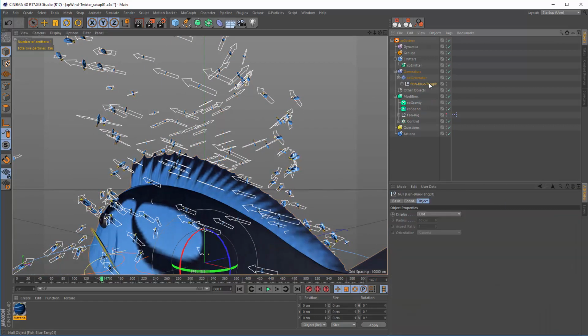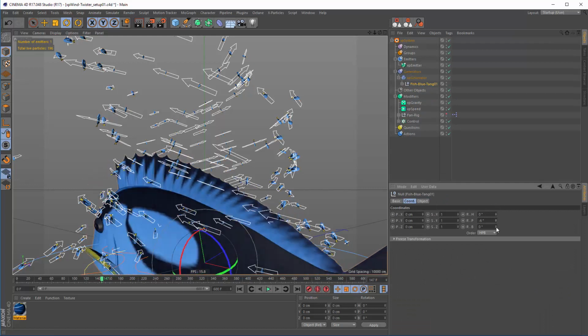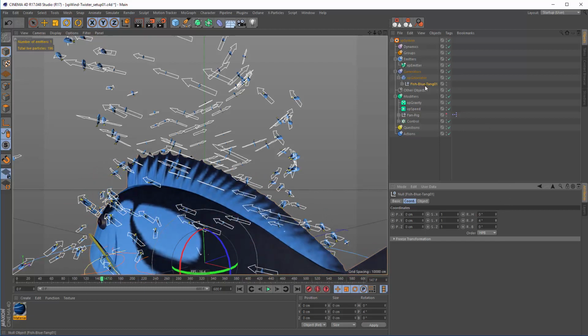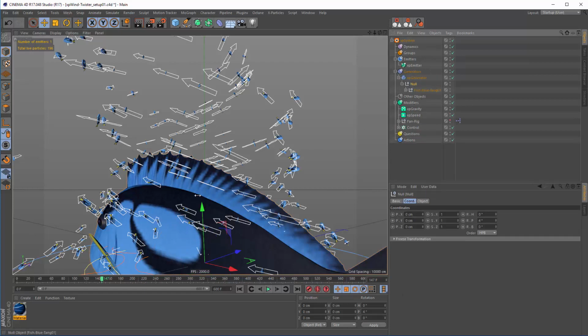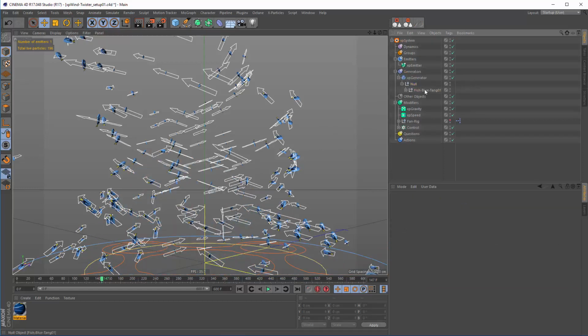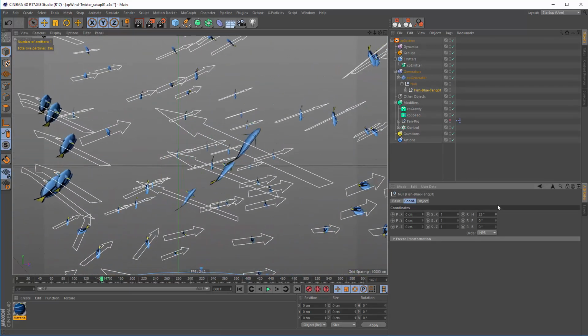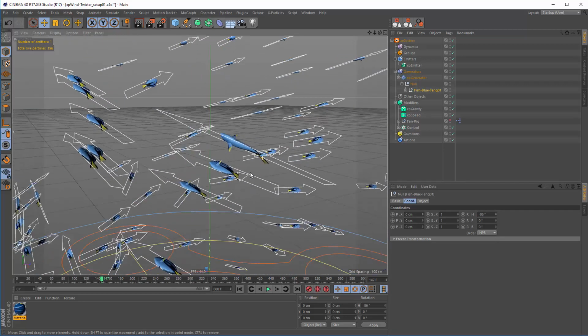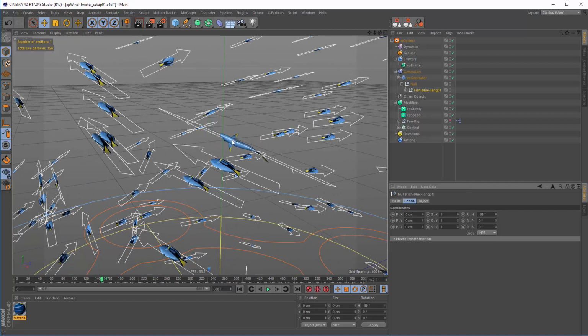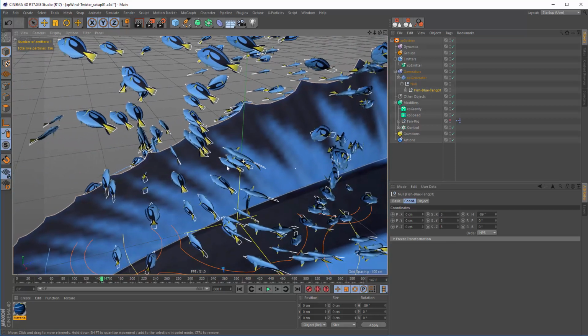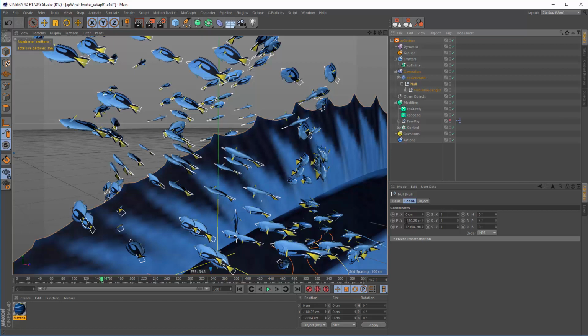All right. So right now, if we want to rotate the fishes correctly, it only affects the source fish. So let's put that into a null object, press Alt G, and let's move that down so we don't see the big one here. All right. And now we can go into our scene and rotate the fishes according to the particle rotation. And we can increase them as well, like scale of 3. All right. And let's move that out of our scene again, like 2000, something like this.